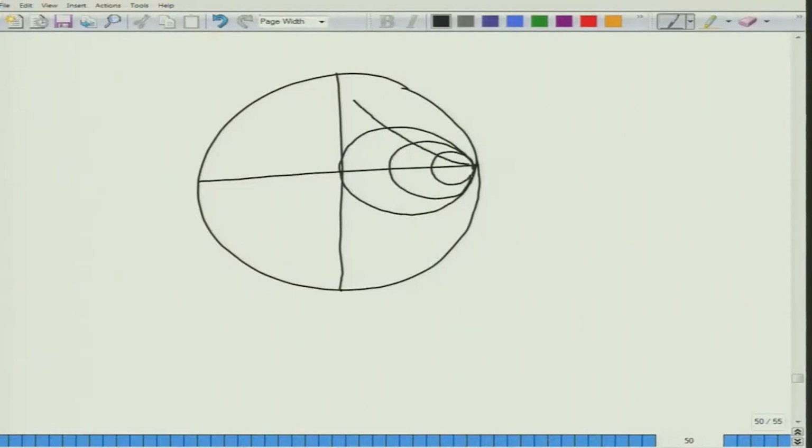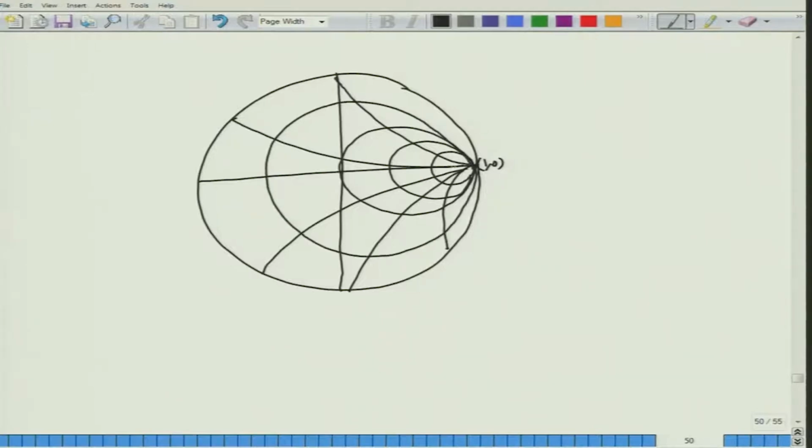And you can also notice a couple of peculiarities with the Smith chart. The Smith chart, all points, will pass through this 1,0 point here. Also, consider the complex impedance Z to be open circuit. For the open circuit, assuming that it is only the real part R that is becoming open circuit, this corresponds to the circle and this corresponds to the radius. The phase angle for an open circuit is also equal to 0. Therefore, this is really the open circuit point on the Smith chart.